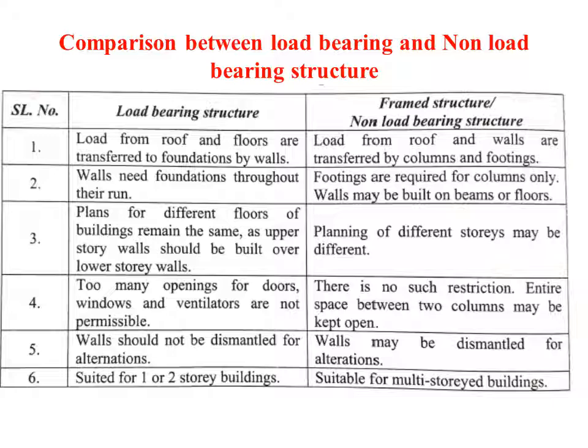Now, moving on to the comparison between load-bearing and non-load-bearing structure. First, let us see the details regarding load-bearing structure. Moving on to the first point, we have the load from roof and floors are transferred to columns by walls, and walls need foundations throughout their run.